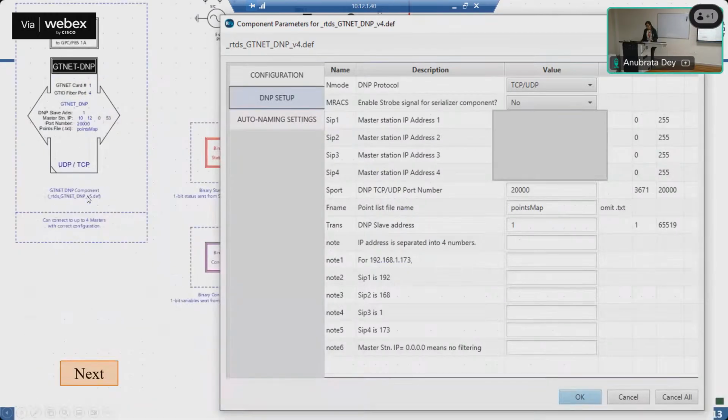For using this, the DNP3 protocol is one in which we have to map each and every measurement. There are 5 types of data points: analog input and output, digital input and output, binary counters, or these kinds of data points. So you always have to map each point till the destination. Like data point number 1 would be our analog measurement and so on. You always have to say which data point belongs to which measurement, and which type of measurement.